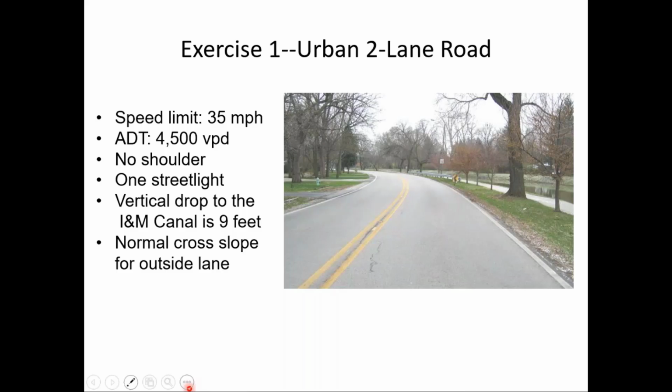Slower speed limit, wider paved shoulder. Curve warning sign and chevrons, possible advanced curve sign, extend guardrail, etc. Yeah, good comments, all good comments.